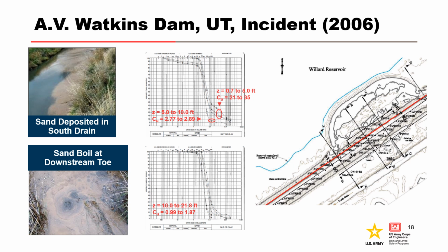Gradation and hydrometer analysis results for PW07-01 at the downstream toe were shown. Below about 5 feet, the soil samples were classified as SP, SP-SM, or SM, with coefficients of uniformity ranging from 0.99 to 2.89.